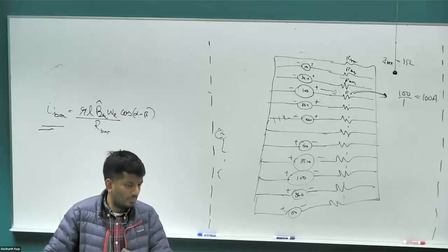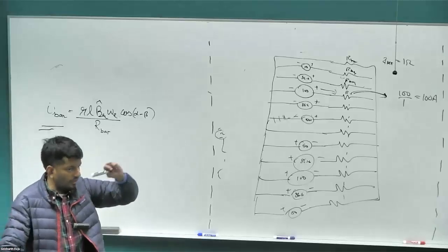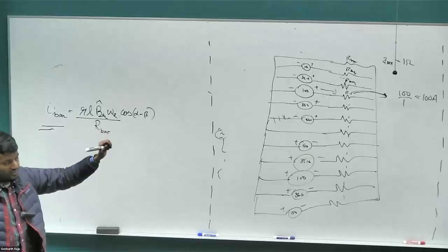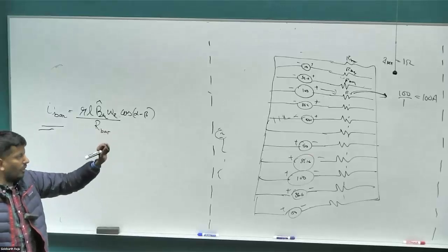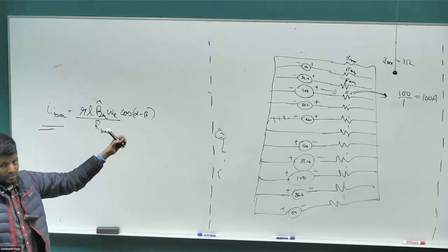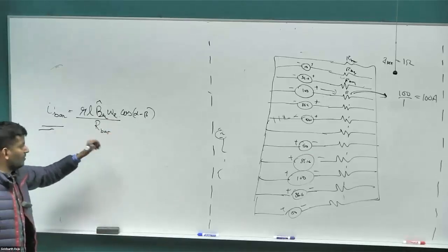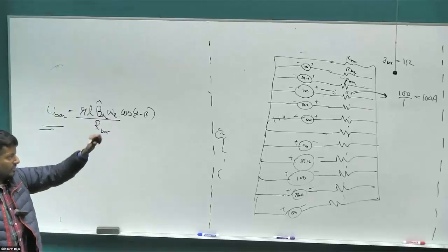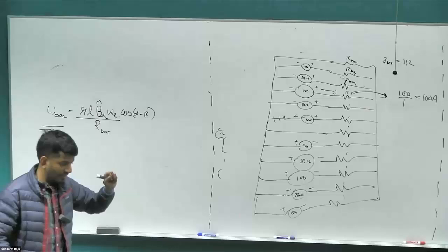Sinusoidal windings. Perfect. The number of conductors in each slot was varying sinusoidally. In the rotor, the number of bars is exactly the same, but just because of the way the motor operates, we ended up luckily getting a sinusoidal distribution in the current, right? And that in turn is going to create a sinusoidally distributed B field in the air gap. The interaction of this field with the stator magnetic field is what is going to produce torque, which we'll